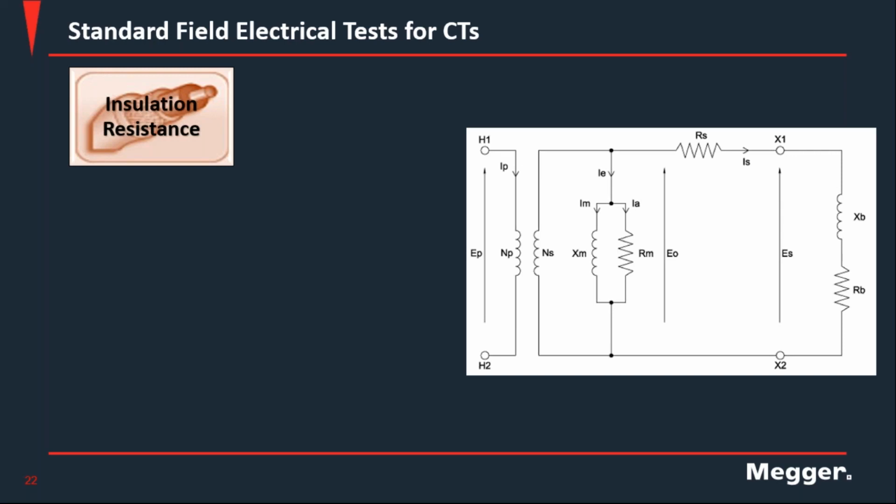But depending on the type of CT or VT, the voltage level, the current level, you may have oil insulation, or paper, cellulose immersed insulation. You can also have resins. So you have different insulations where sometimes a simple insulation resistance at 500 V or 1 kilovolt may not be enough. You need to consider other insulation assessment tools.